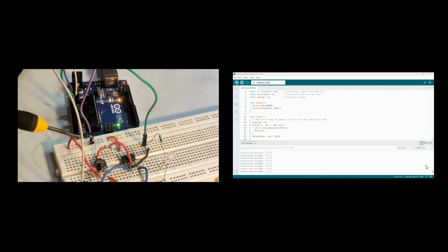Before that, I will just tell you what a Wheatstone bridge circuit is. These are the two resistors connected as a Wheatstone bridge. Please remember that. And this resistor also is connected in the same fashion. Instead of PT100, I have used a thermistor here, and then a 100K feedback resistor. I've also used an LED light so that you can see how the LED comes on when the voltage is increasing.